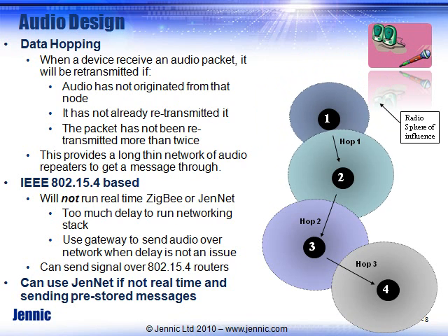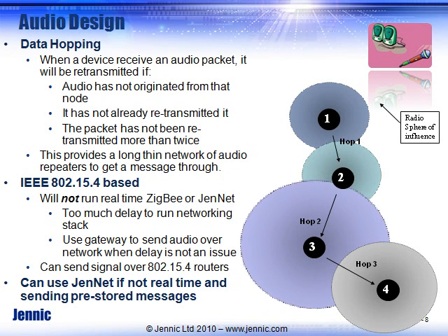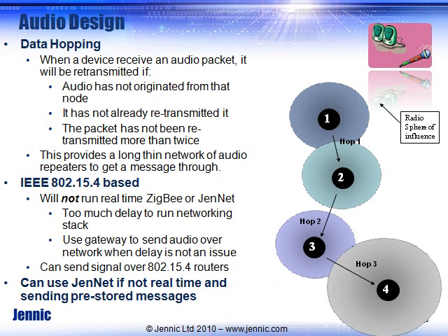This next slide shows you with animation exactly how our system works. It is based on a hopping scheme so that the first radio, number 1, transmits its audio information. Receiver 2 receives it and retransmits it, so all users then see it within its radio sphere. They see all of the data and so forth, and it continues hopping. We feel you can get good audio quality with 5 to 6 audio hops.